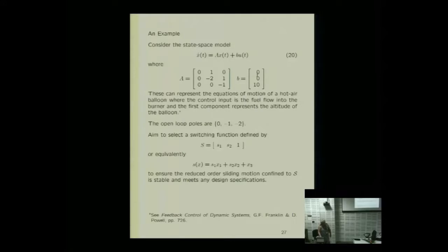Let us think about selecting a sliding surface, and let's think about taking a linear combination of those three system states. Now here, note that that's defined by two parameters. If you think about the previous example, I was trying to control the double integrator, which was the second order system, and I picked one parameter, m, the slope of the sliding surface, to define the dynamics. Here, the number of parameters has reduced by 1.